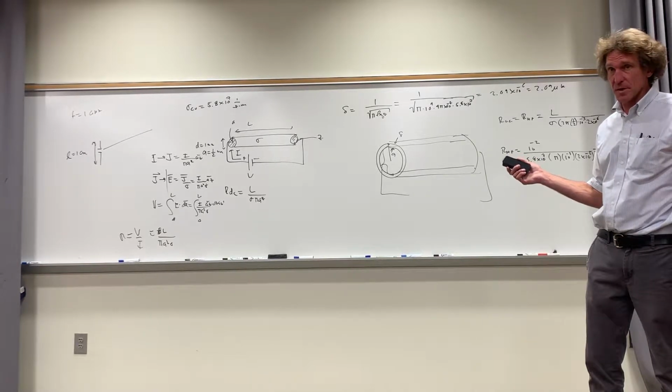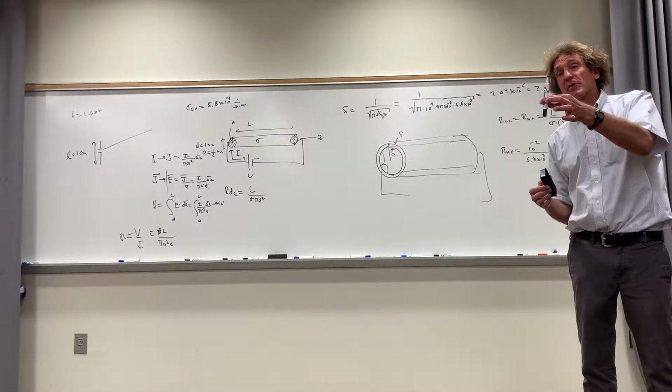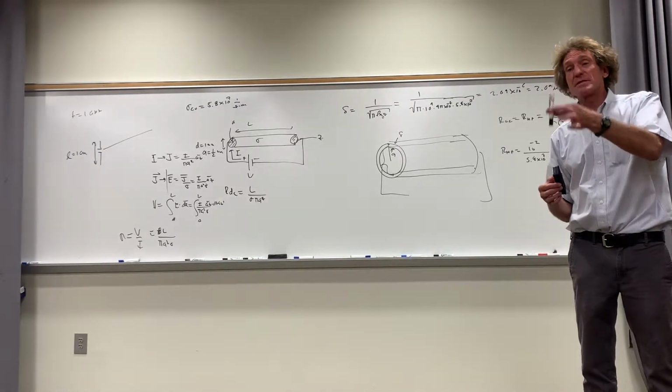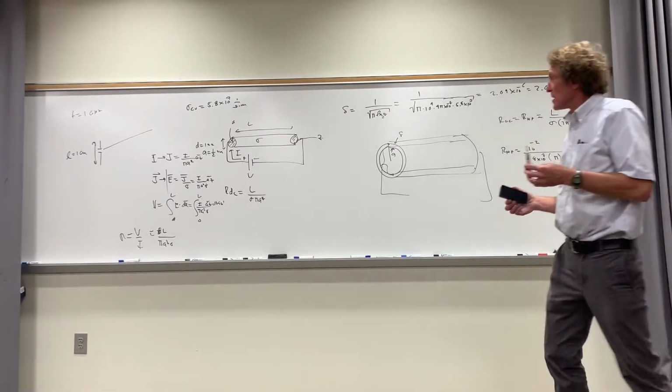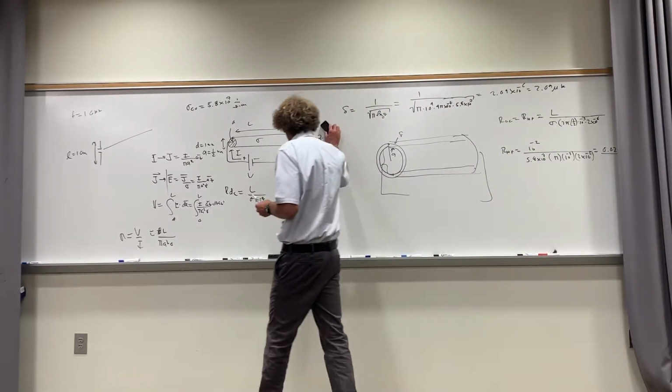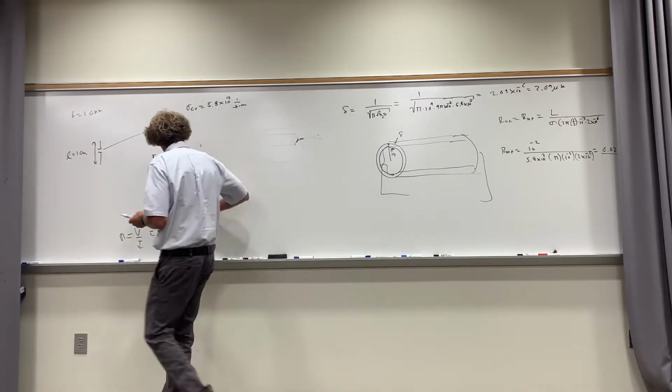Does this make sense to everybody? Because it's at a high frequency. Is everybody all right with this? I want to make sure I'm not assuming something. It's just a piece of wire, but now at that frequency, all the current flows in one skin depth near the surface, right? Okay. Now that's DC and that's AC. You want the AC resistance. You're dealing with antennas generally.